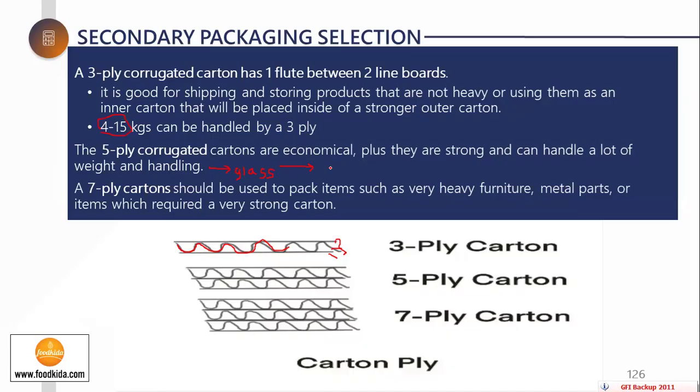They are 5-ply cartons. Why? Because you unitize 48 sachets of 25 grams. So you have a strip, which you convert into a mat, and then it is packed into a poly pouch again. In this case, your laminate is your primary, the poly pouch inside the carton is your secondary, and the carton outside is your tertiary.